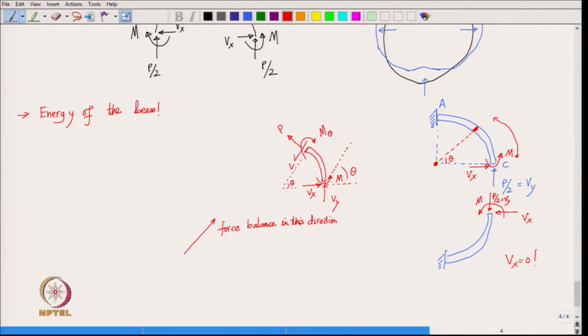So, shear force is acting opposite to this direction of force. So, we get minus V, right, and then we have the components of Vx and Vy in that direction. So, how much would that component be? The component of Vx is simply Vx cos theta. So, it gets plus Vx cos theta, whereas the component of Vy is Vy sin theta, and both come with positive sign. So, this is equal to 0. So, this implies your V is equal to Vx cos theta plus Vy sin theta.